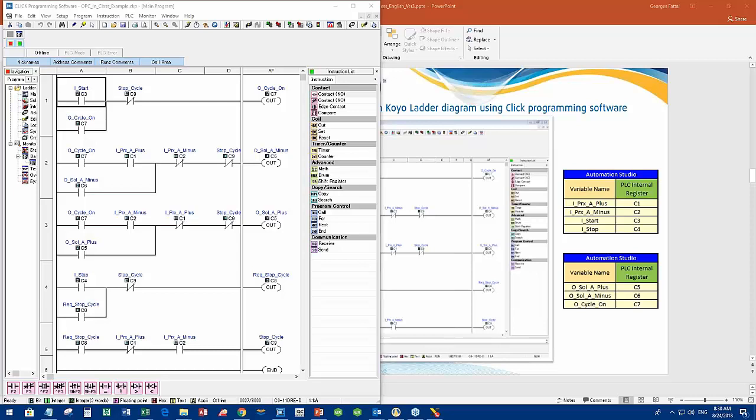The thing of using the macro to generate the CSV file to import it into Automation Studio, he can use his own way of doing this CSV file. Excel is one way of doing it, so that's why I used Excel for it, because a lot of people are using it. But sure, we can share it and make it available, because the same Excel sheet, as I'll show you later on, will be used to do the assigning and the tying OPC items with Automation Studio variables. So okay, that we can share, yes, with the customer base.